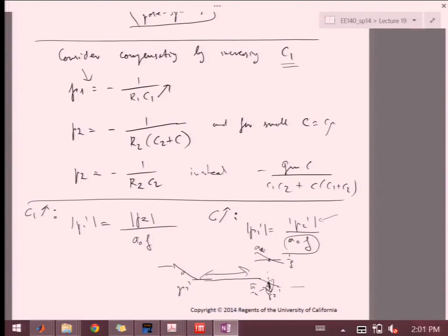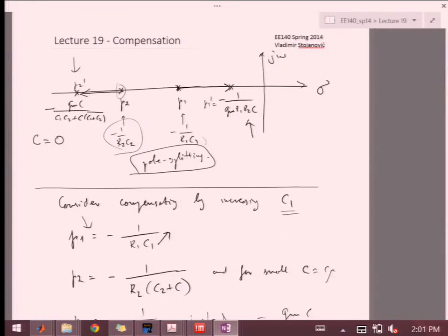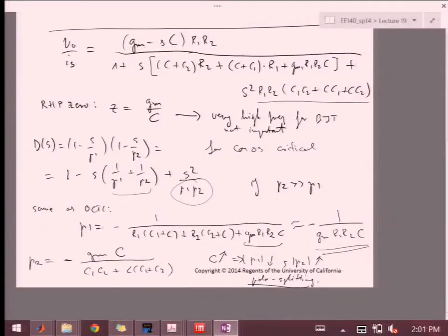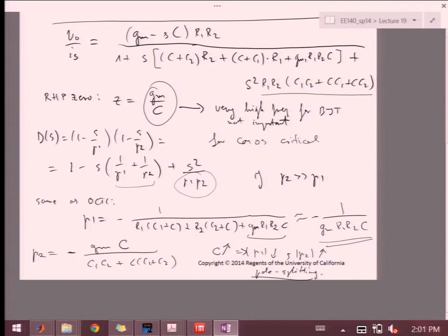Because, as I said, some of these tricks that we're doing are not going to work exactly out of the box for CMOS, simply because of this right half plane 0, which we could neglect in bipolars, but we cannot neglect in CMOS. So we'll have to do a little bit more complicated compensation over there, but you'll kind of understand it when we get to it. OK.